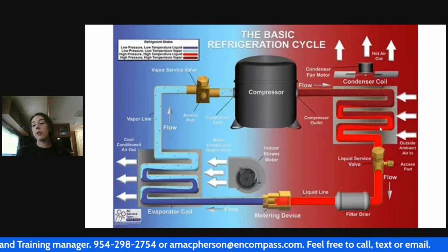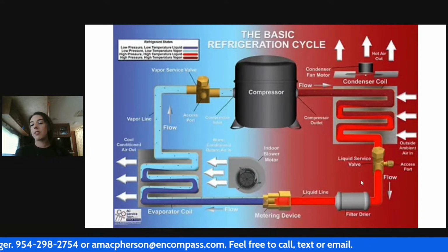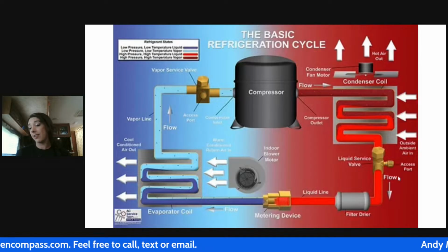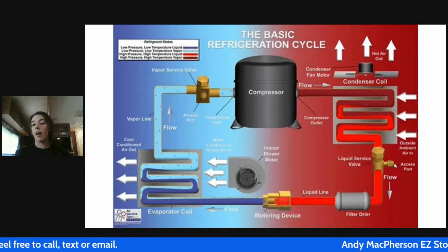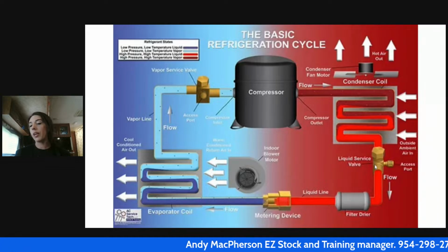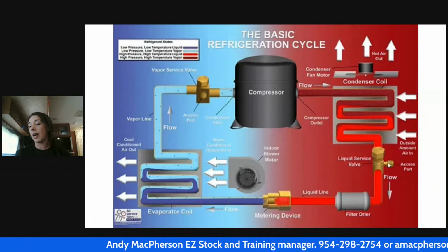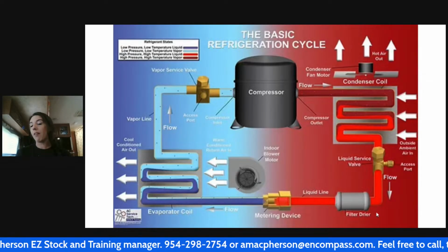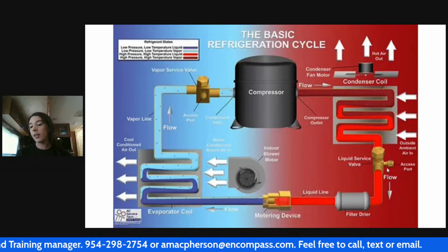You can see a liquid service valve here. This is not considered a component, and that's because all it does is allow us to access inside the system to test. It does not create any change within the system. It's just a flow through. So even though it's a service valve on this side where we can hook up and manipulate it a little bit, going through that valve for the refrigerant itself is just a pass through.